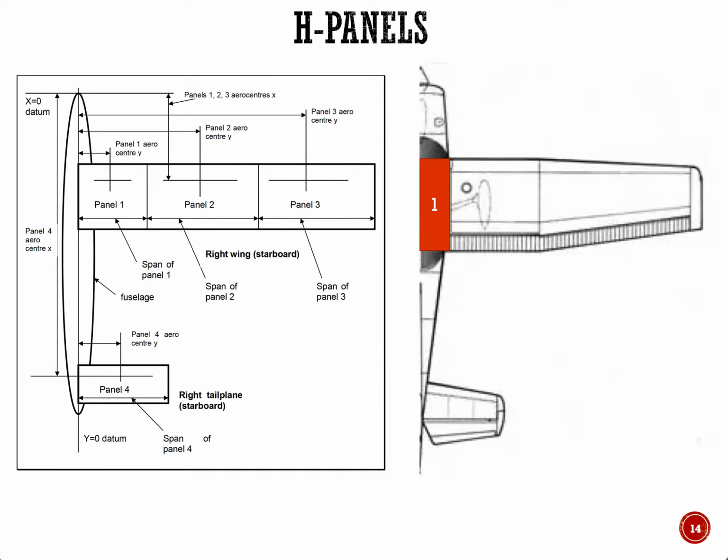All right. So it's important to know how the simulator models the wings. The simulator uses symmetry. The simulator models only the right wing, and then uses symmetry to model the left. So in other words, you cannot model an asymmetric aircraft, like a slewed wing, like an oblique wing, in the simulator. It doesn't work. It works based on symmetry, and you better make sure the airplane that you're designing is symmetric about this y-axis.